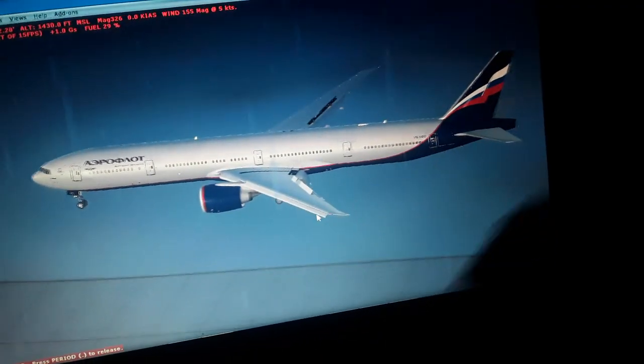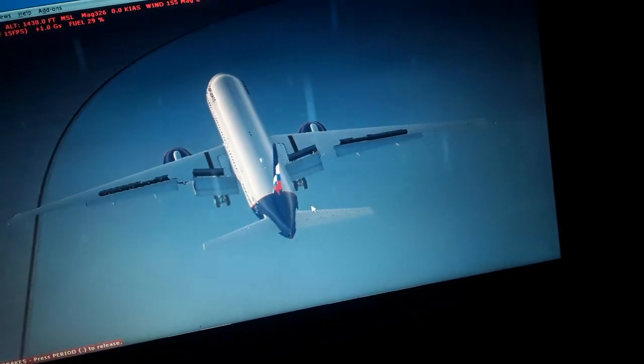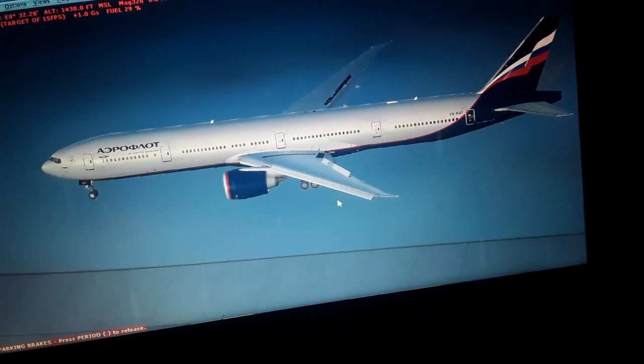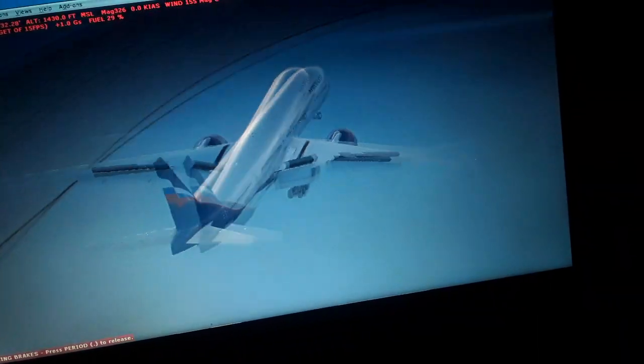So I'm going to show you now a couple more things. So these are the main principles about the aerodynamic lift and flight theory of the airplane. I'm going to show you now the flight controls very quickly, how to use the side stick or the yoke. Depending on if you're flying a Boeing, you use the yoke. If you're flying an Airbus, you use the side stick. If you're flying an Embraer, you use the yoke again, to steer the airplane.